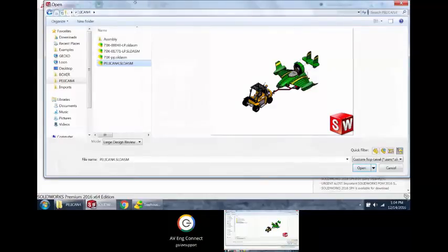Yes, sir. Do you need to be in a vault for that to work? It works in local files and vaults. You do need to go through the file open. If you double click out of Windows Explorer, it's going to ignore that and just load up everything resolved, which is the slowest way to do things.